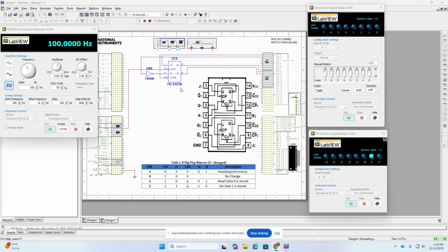Also, this device is a negative edge trigger, just like the 76, meaning that it changes state on the high to low transition of the clock signal. So the key difference from a standard JK truth table is that for the D flip-flop operation, K must always be opposite of the logic state. And what I've done here is I've already run through the cycles. I put the outputs there, so you can see the image of what to expect on the operation of this.